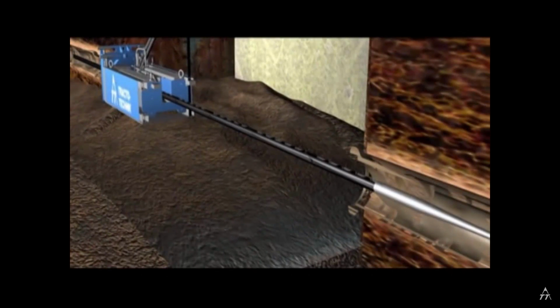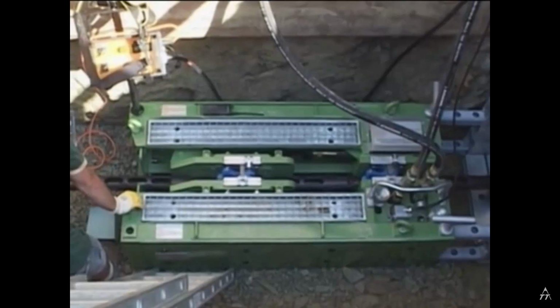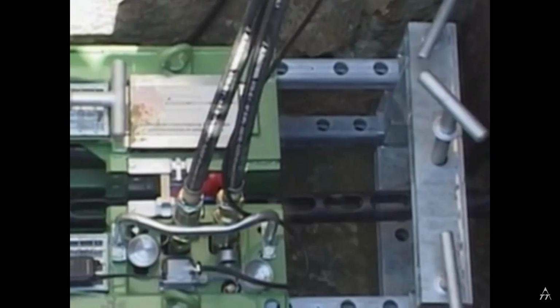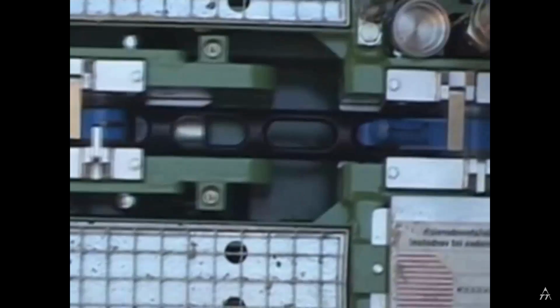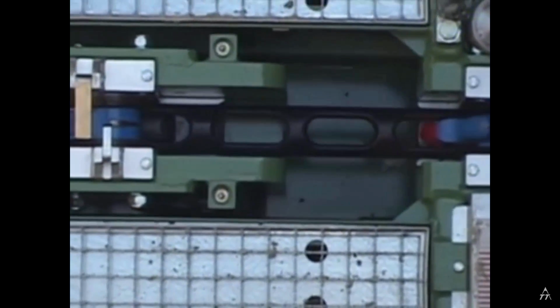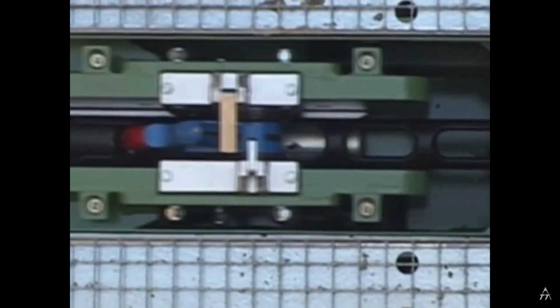Under favorable conditions, the rods can be pulled back through the rig and simultaneously pushed into the rear-facing mains, ready for the next bursting operation. A highly productive solution. The time needed for the rod string assembly and disassembly for an entire two-way mains replacement length is thus saved.